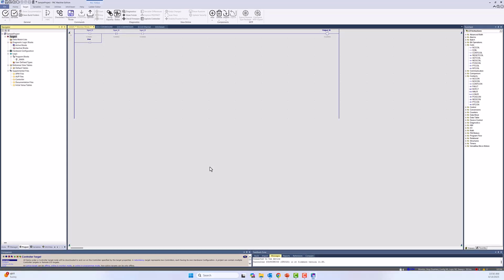And just to highlight that, if I look at the properties, typically when I'm connecting to a physical controller out there on my desk, I would need to put the method of connection. So for physical port, either COM 1, 2, 3, 4. In this case I've selected Ethernet. But notice that even though I've selected Ethernet, I don't have an IP address. It would yell at me if I weren't connecting to the simulator because I need a physical IP address to connect to a controller on my desk.